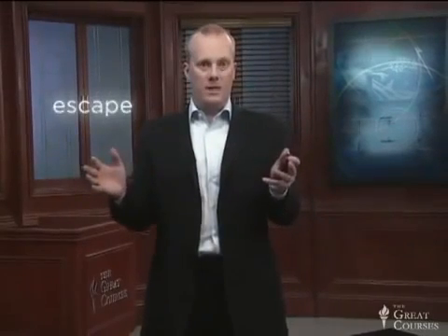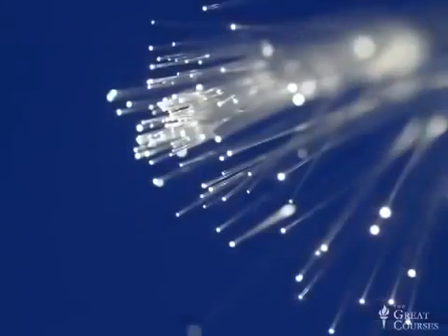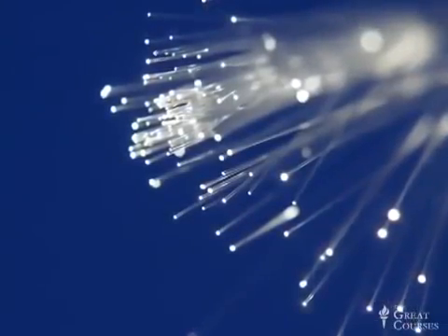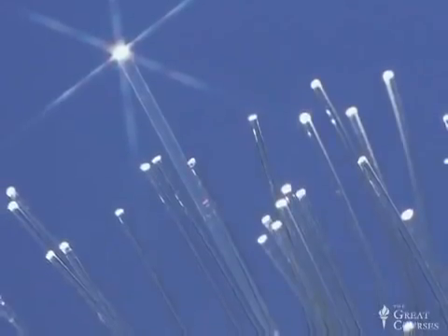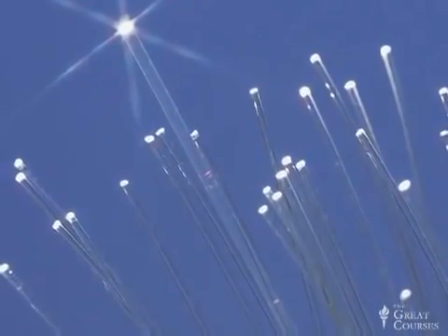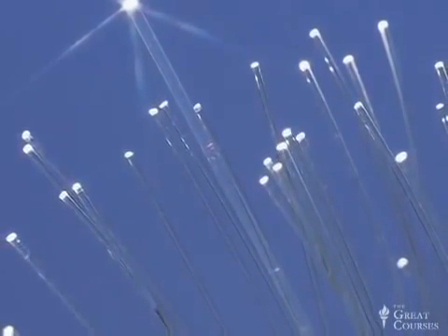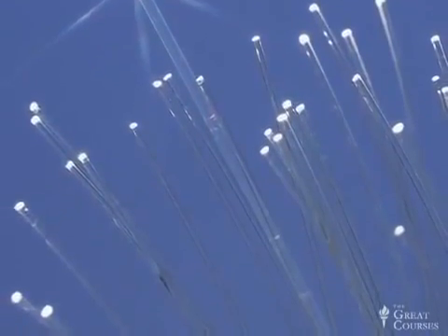How do we engineer that quality? Well, this is really all about creating an optical environment in which light has two options. It can either propagate or it can be lost. It can escape. And then our job in creating the source of light and shining a beam of light into one of these optical fibers is to excite only this one mode, where light can just race down this fiber without impediment and at a single well-defined speed.